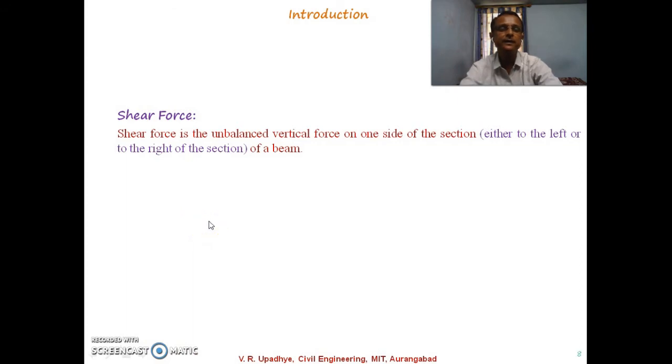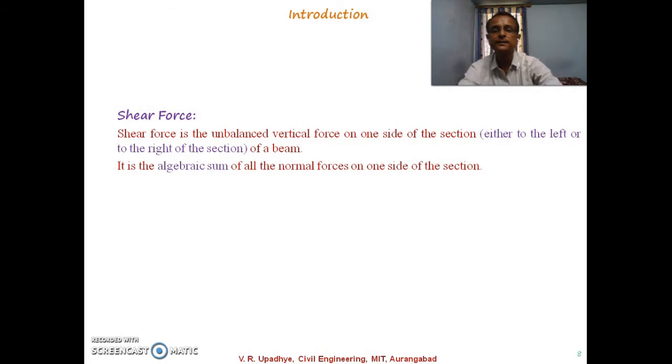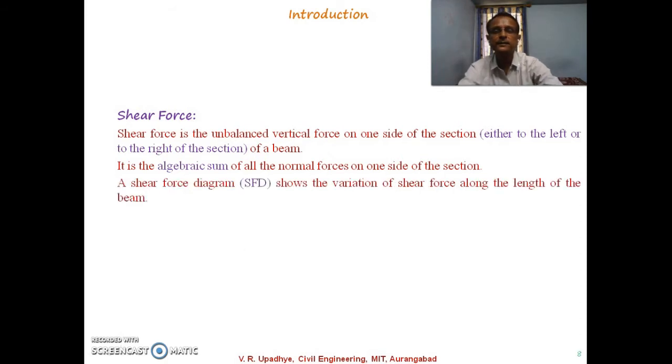It may be considered either to the left or to the right of that particular section of that beam. So it is the algebraic sum of all the normal forces on one side of the section. A shear force diagram, SFD, we will be discussing henceforth. It shows the variation of shear force along the length of the beam.